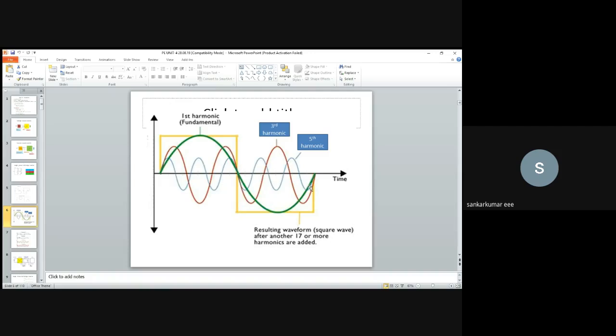A pure sinusoidal inverter will give the output voltage in sinusoidal nature, but in practical cases, in most inverters we obtain only square or rectangular waveforms as the output. So that is the impure form of AC. According to Fourier series analysis, the square waveform comprises one pure sine waveform. In addition to that, we have some additional frequency components, which lead to the distorted nature of the output. If we extract the pure sinusoidal waveform, the remaining terms will be multiples of that frequency.